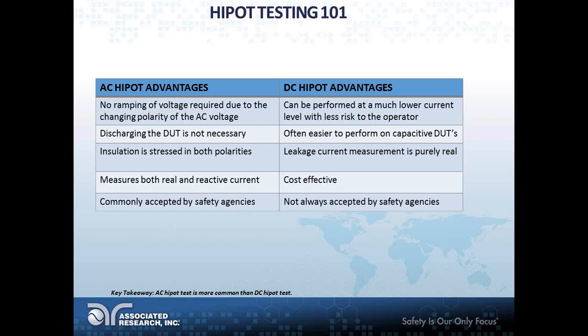Once the capacitor is fully charged, the current across the capacitor is approximately zero. So there's no reactive current flowing. Therefore, with the application of a DC Hipot test, the current value, that's the leakage current that's measured, is purely resistive. DC Hipot testing is more cost effective, but it is not always accepted by safety agencies.